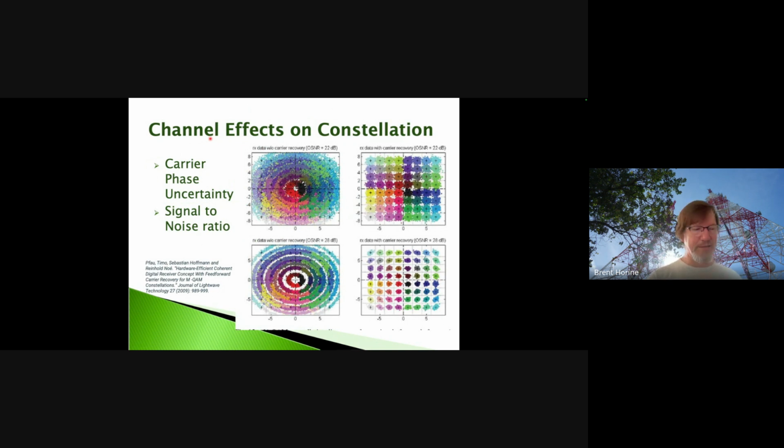As you transmit that signal from the transmitter antenna to the receiver antenna, it's going through 2 pi radians of phase shift for basically every wavelength of distance as that wave propagates from the transmitter to the receiver. And the likelihood of that being an exact integer number of wavelengths is extraordinarily low, right? And so you're going to have some arbitrary phase shift on that waveform at the receiver, right?